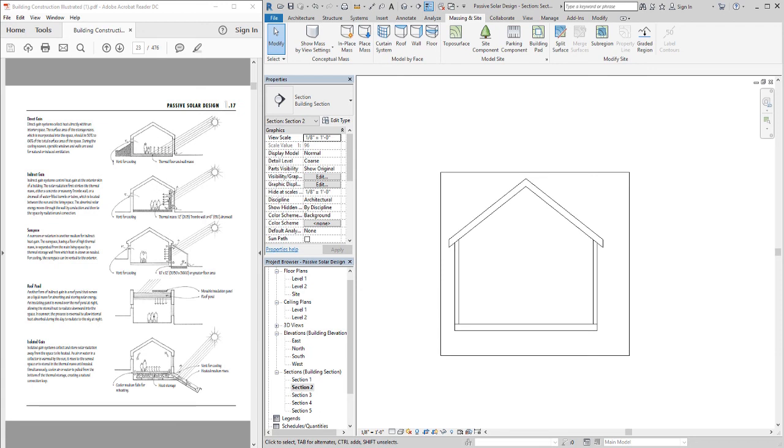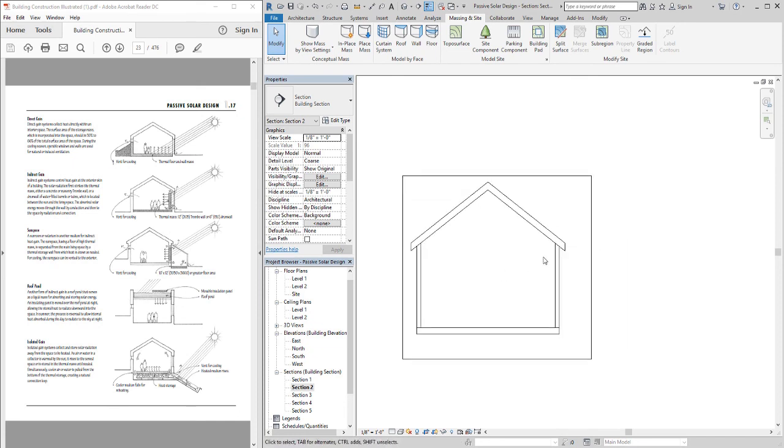So essentially we're going to have almost like a trombe wall here to absorb that heat and then radiate that out into our space, where direct gain was more so like the actual floor and walls of our structure, where this is going to allow a little bit more conduction to just kind of pass this through. Not necessarily convection where air is moving through. That's going to be more isolated gain. So very similar, but not to be confused with it.